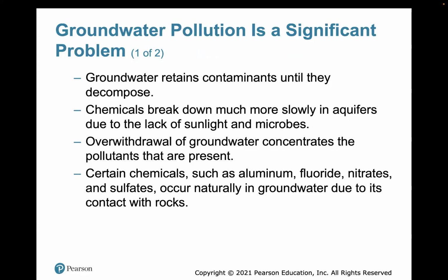Pollutants may reside in groundwater longer than surface waters because groundwater is not exposed to sunlight. It has fewer microbes and minerals that hold less dissolved oxygen and organic matter than surface water, and pollutants decompose more slowly. For example, the concentration of herbicide declines by half in 20 days in soil, but in groundwater, it takes almost 4 years.